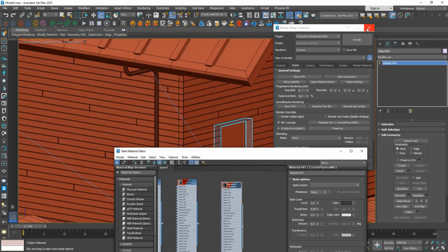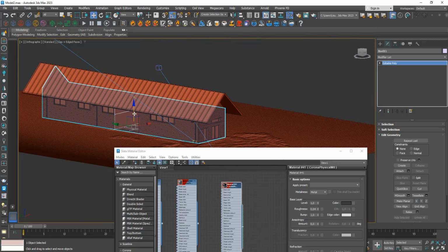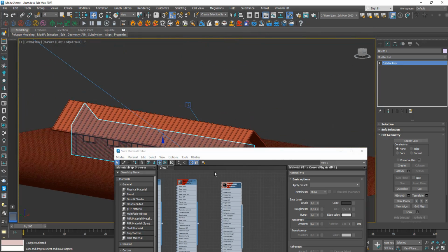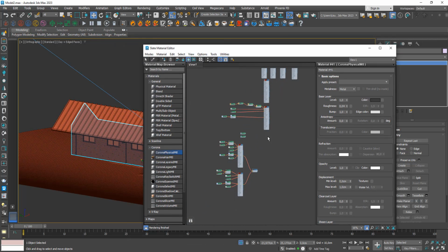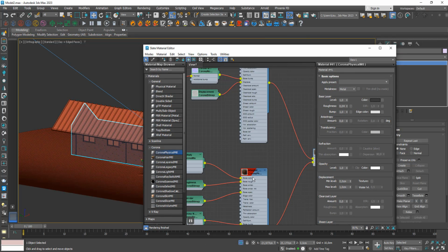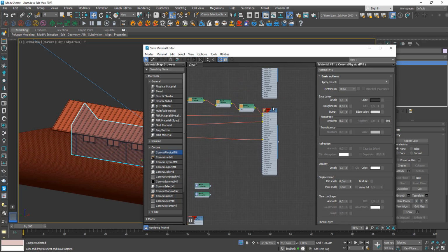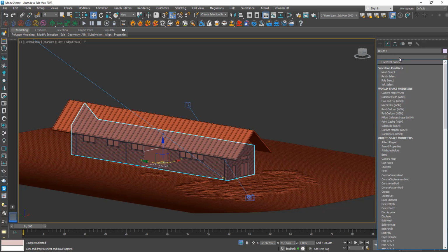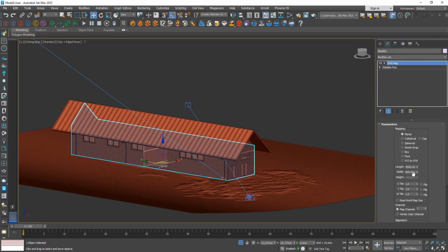I'm going to select the whole architecture like this, which is this shape right here. And I'm also going to be adding a wooden texture to it, which is the one that we already have. And it's actually all the way up here. Let's map it too. So UVW map. Let's use the box. And remember that we've been using these dimensions, 250 by 250.